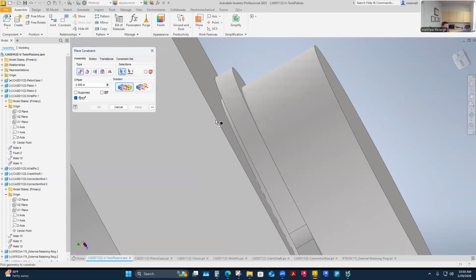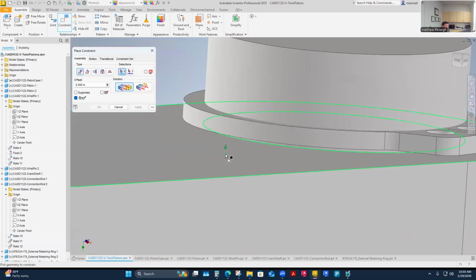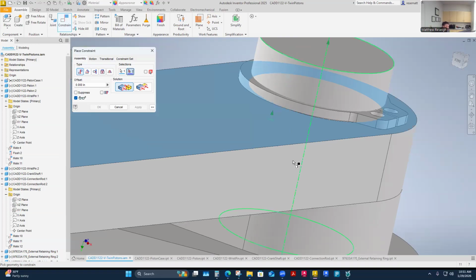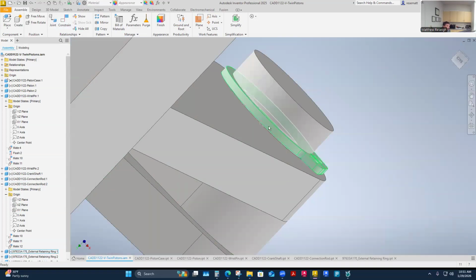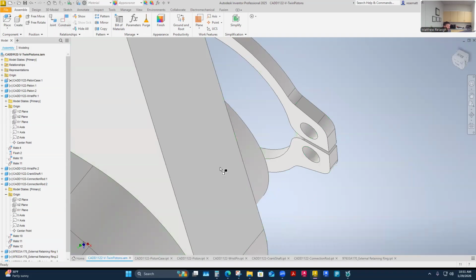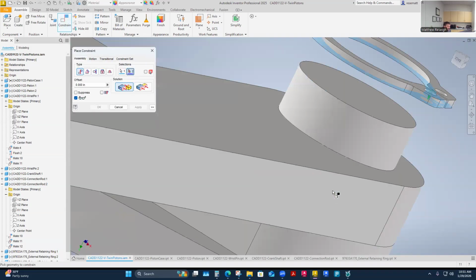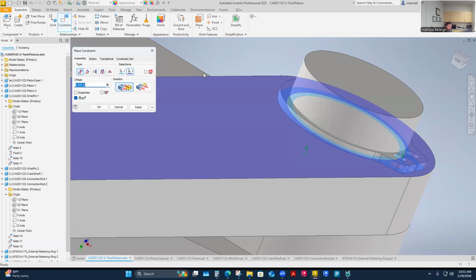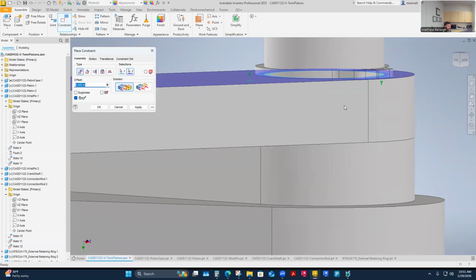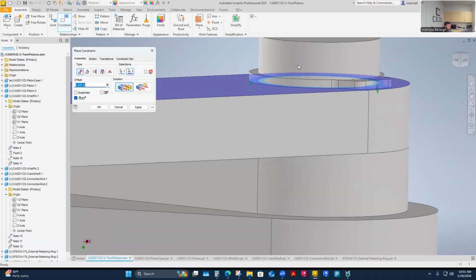From face to face, like from here to this other face. If this gets hard for you to do, it's easy to get out of the constraints. You can pull this away so I can get to this other face. But what I'm considering is a constraint from this face to this top face here, instead of being slammed down like this, where I could get some binding. These are all slammed together now, and if my groove in my crankshaft is right there, then I don't have a lot of tolerance creep.